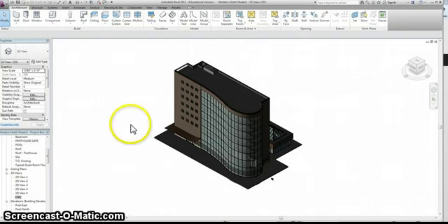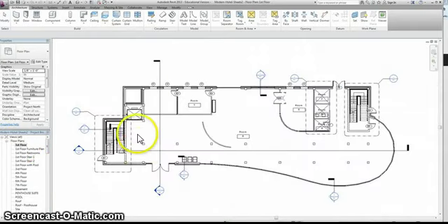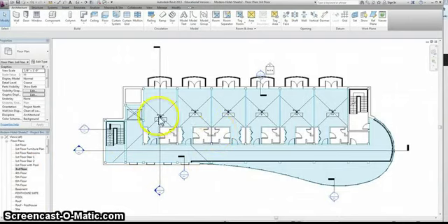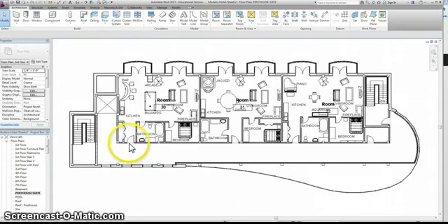And the first thing we need to do before we can get that into Ecotect is we need to go into the first floor view plan, and we need to tell Revit that each room we built was a room. So click room, and you'll select each room so that Revit can identify that these are rooms. This will allow Ecotect to identify and run analysis on these rooms as well. So make sure you go through every floor and select every room. And here's the 8th floor.